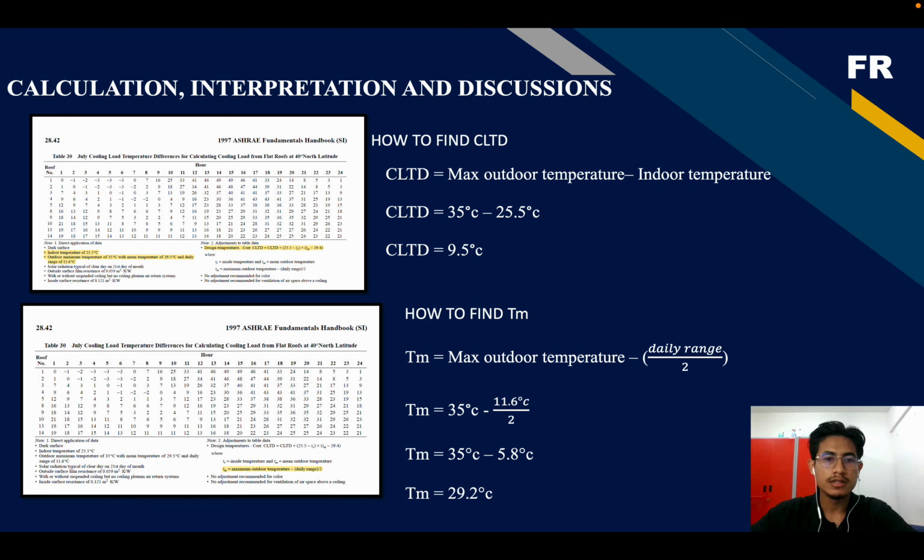Today I want to present how to calculate, interpretation and discussion. The first one is how to find CLTD. You can find it in ASHRAE chapter 28, table 30. This is how to calculate CLTD. And the next one is how to find TM, also in ASHRAE chapter 28, table 30.